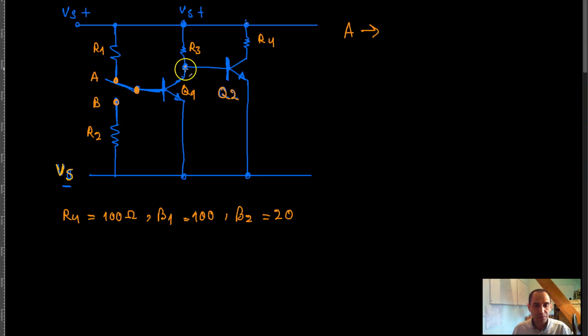And so what that means is that now there is no voltage on the base of this transistor, and when there is no voltage on the base, there is no current through the base, through emitter to the ground, and as a result the transistor is of course turned off, right? So that means that Q2 is, in this case, off. And of course in the other case the Q2 is automatically going to be turned on, but we will go through that as well to show you how you can think about this in such a way that your line of reasoning works.